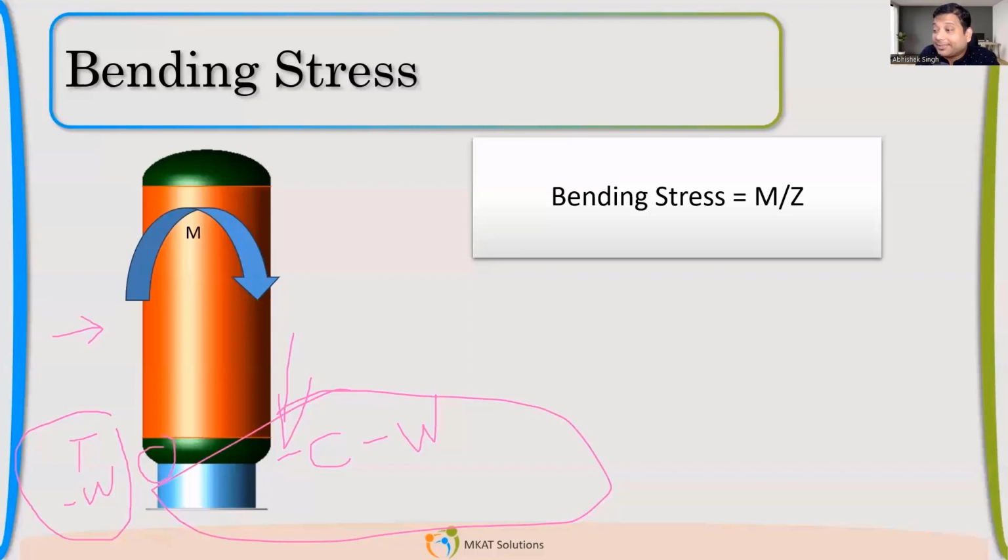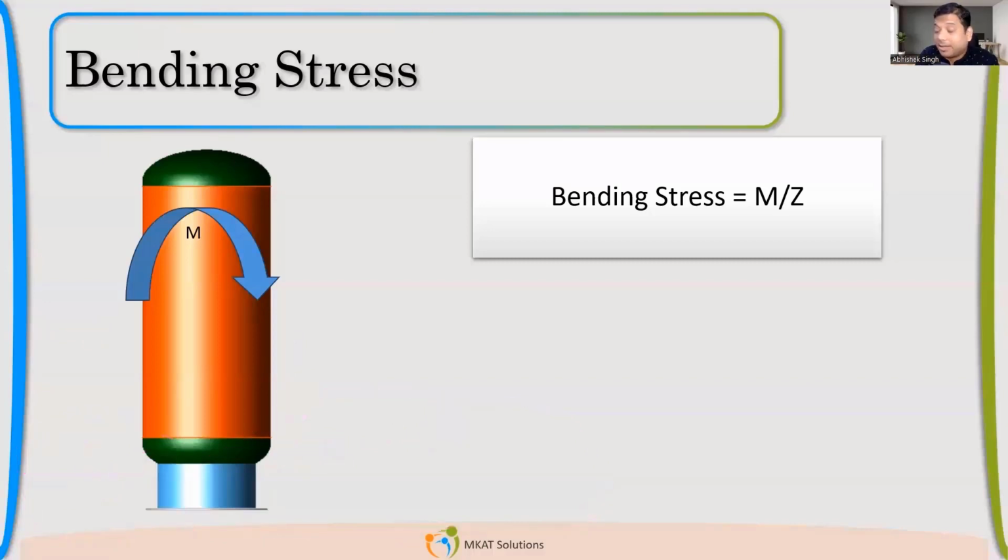Okay, because in the empty case, your minus this W will be smaller. That weight is quite less compared to the hydrostatic test time. While in this case, if your weight is small, your moment may start governing. So tension may start governing. So unless you calculate, you cannot specifically say which case will be governing. So you have to calculate to know about it.